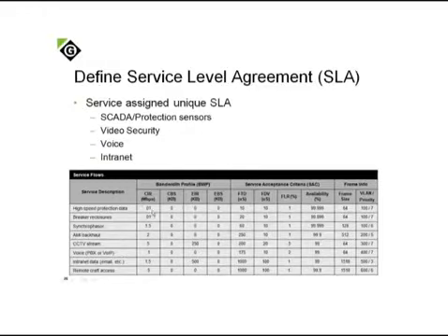If we think about committed information rates, your high-speed protection data is typically a very slow but reliable network: 64 kilobits, 128 kilobits, very slow data. We absolutely do not allow it to go into the excess information rate bucket, because we want it committed to that green frame. It has very low frame transfer delay. We need low latency and low jitter, and we absolutely can't lose more than the 0.1% frame loss ratio, so it can't have frame loss that exceeds a certain threshold. And of course, five nines availability. Service always has to be available.